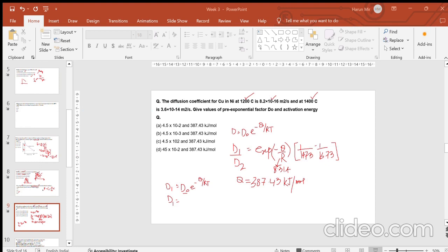So obviously you have a concentration gradient, because as the carbon diffuses inside your steel specimen, it will try to increase the carbon percentage. On the surface we will have a very high carbon percentage, and then it will decrease up to like 0.2 inside the specimen. So you have to calculate at what distance x of the specimen you have a carbon percentage of 0.48 after you have carburized it at 870 degrees for 110 hours.